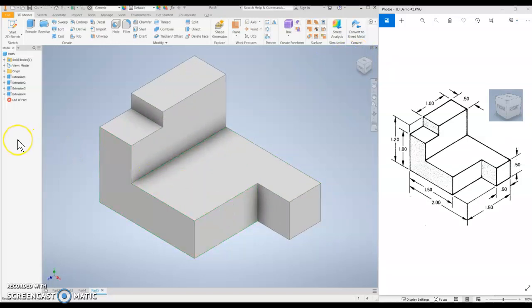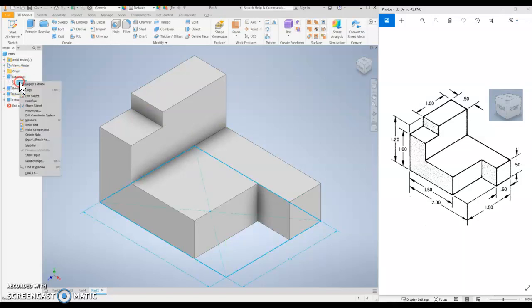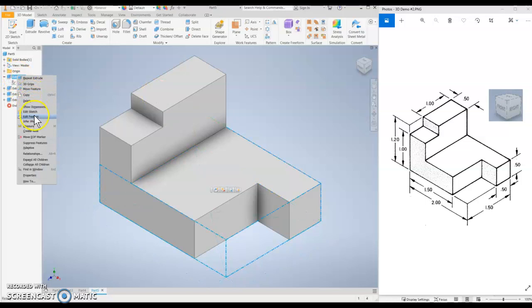You can see all of your sketches and extrusions by going down the side here. So the first one was that base block that we built. We did 1 sketch. You can always highlight over your sketch and see your sketch. If you want to change that, remember, you right click. You can edit your sketch to adjust the size, or you can edit your feature when we go to our extrusion, and that will allow us to change how high we extruded it, or what we extruded perhaps.